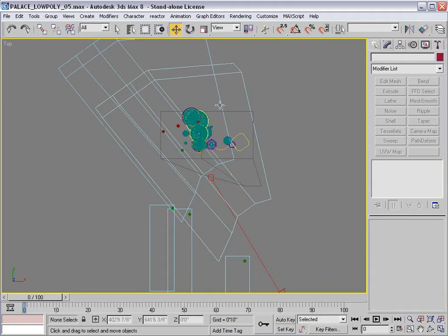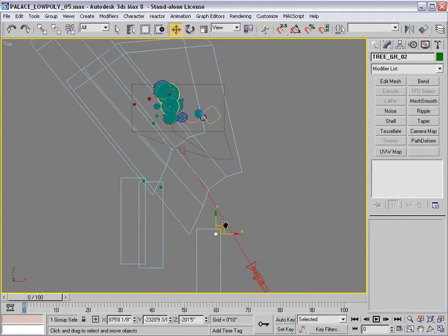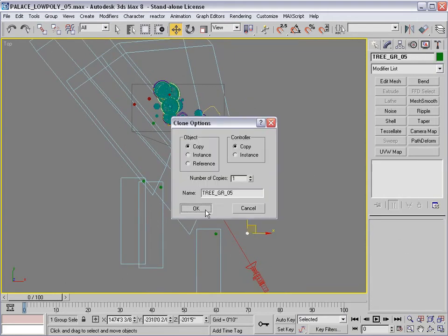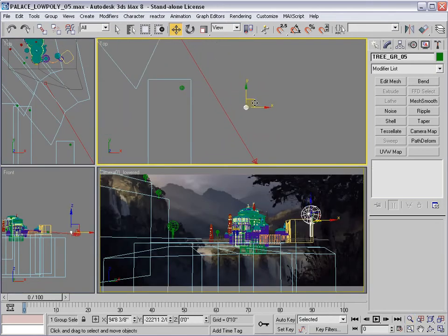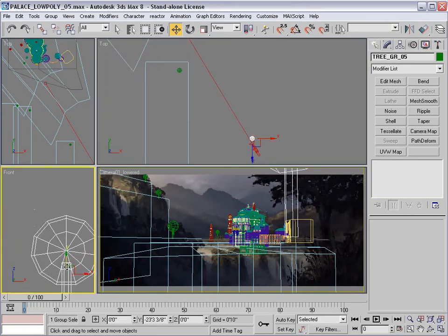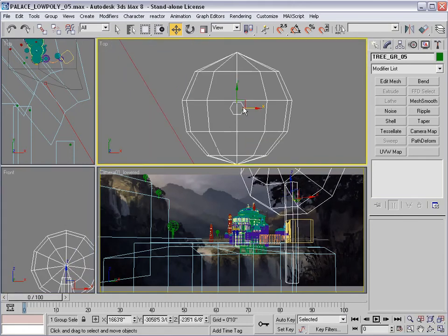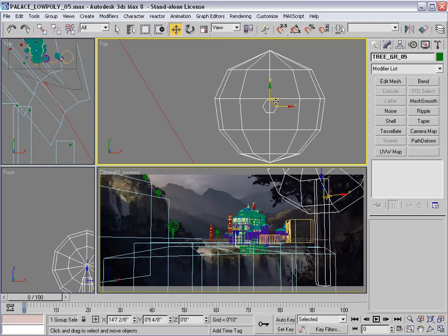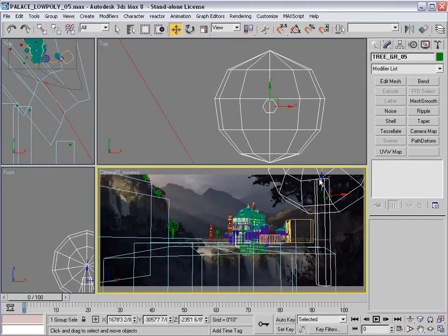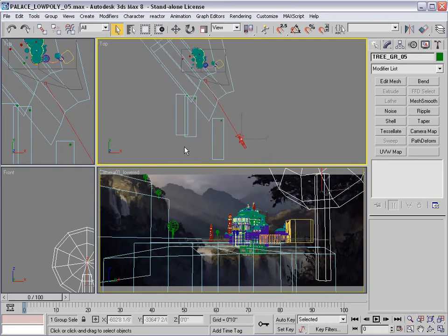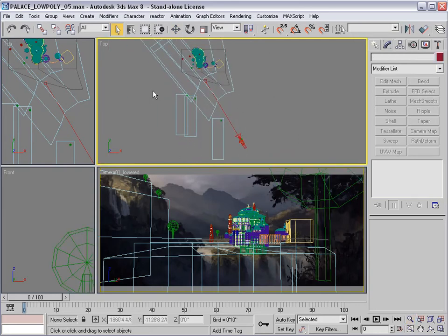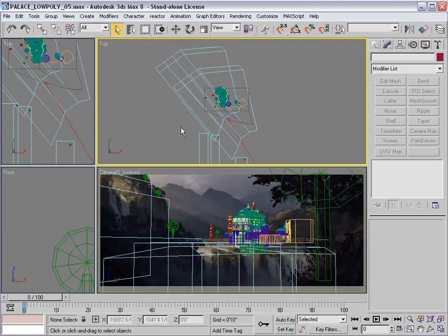What we're doing is we're giving the camera map, our texture maps, a self-illumination in Max. I believe it's called an incandescence map in other programs. But what it is, it's essentially a map that is not prone to any lighting or shadows. It can't catch any shadows because it's brighter than another object that would have that ability.